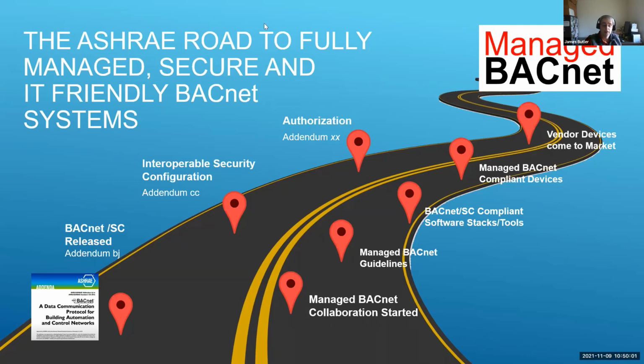We probably don't have time to go into all the details, but BBMDs only forward broadcast messages in a BACNET IP system. BACNET SC hubs, which by the way can be anywhere in your system, don't have to be on the same subnet as your existing devices. The BACNET SC hubs forward broadcast messages, but they also forward point-to-point messages between devices that are not communicating on a peer-to-peer basis.